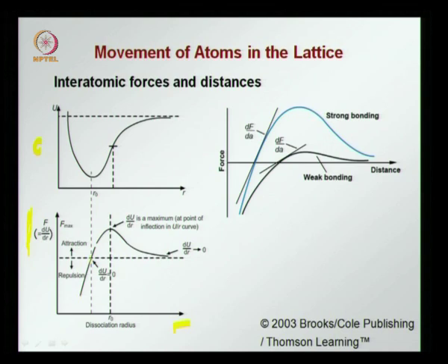Here the atoms are closer to each other than the stable distance r0, and then as there is more tension, or the separation of spacing with r being greater than r0, you have this curve which is on top of this dashed line. This point corresponds to the place where you had the minimum energy, and this corresponds to the zero force situation where the atoms are separated at a stable distance.